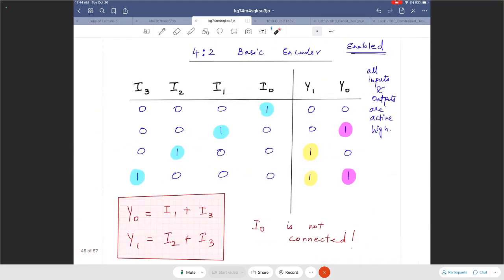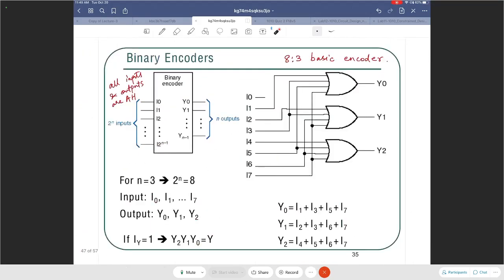If you expand this table, instead of 4 things to 8 things, and instead of 0 0, this being 0 0 0 all the way to 1 1 1, you are literally saying the least significant output alternates, the next to that goes half the speed, and so on. So those numbers are essentially going to be 1 3 5 7 alternating, 2 3 and 6 7, right? 2 off, 2 on, 2 off, 2 on, and then 4 off, 4 on.